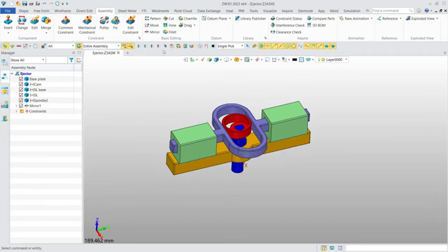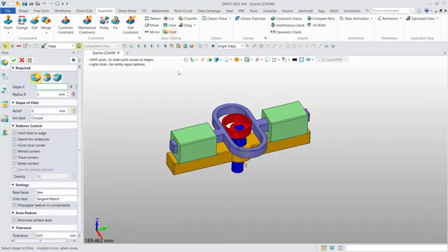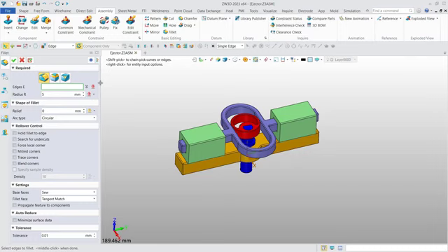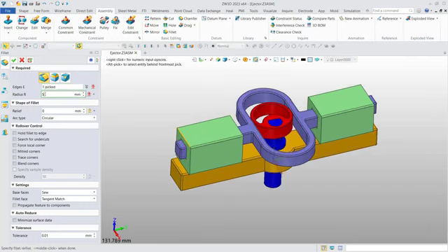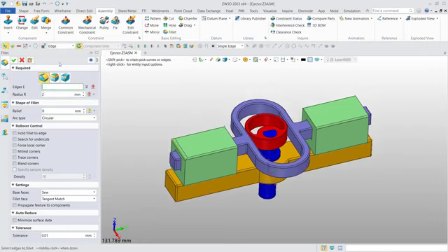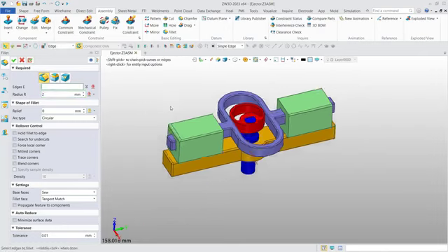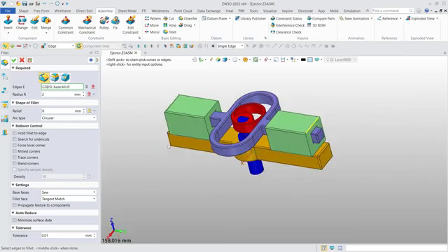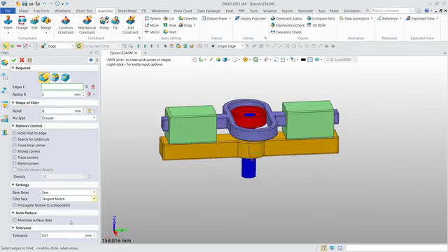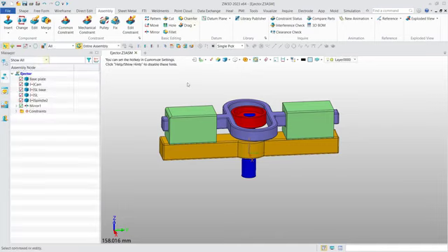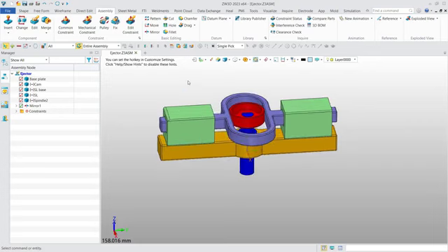And for assembly fillet, it's similar to use as the shape fillet. Okay, we select the edge, and we select the radius, and click OK. We can get a result. And the same, you can decide whether to propagate to the components. Okay. And the chamfer is the same. I'm not going to repeat it. Okay, this is all for the assembly features.